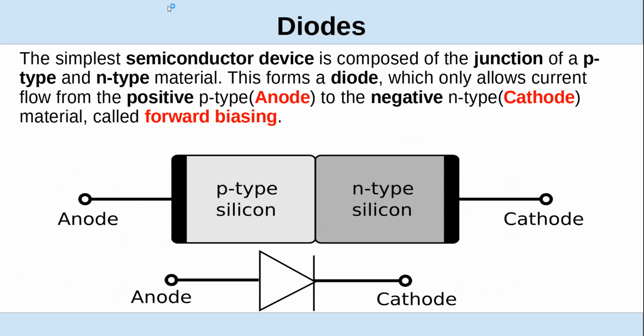They discovered when they put two of these pieces together, a p-type and an n-type, it would act like a diode, just like in the Fleming valve, and it would conduct current in one direction from anode to cathode, the conventional current. The electron flow goes the other way. Because of that barrier between the two, there's a little bias voltage or an offset.